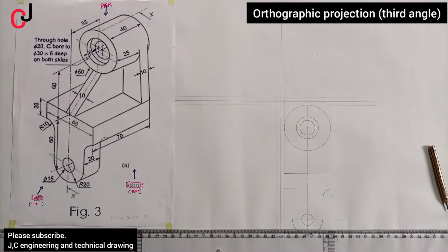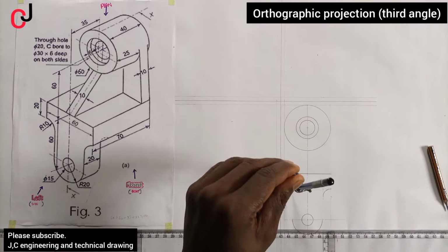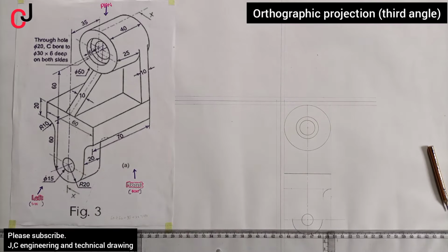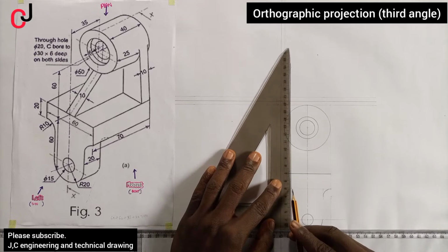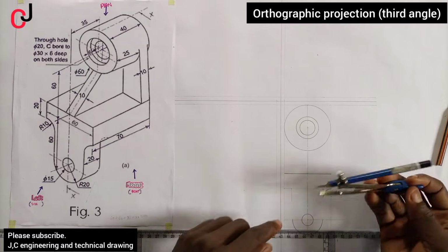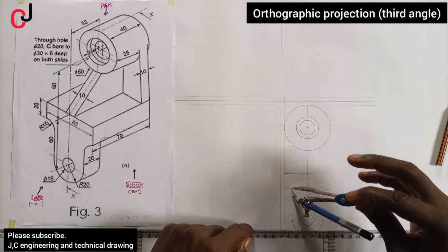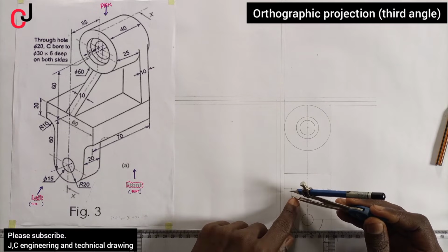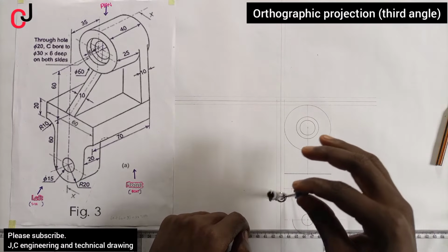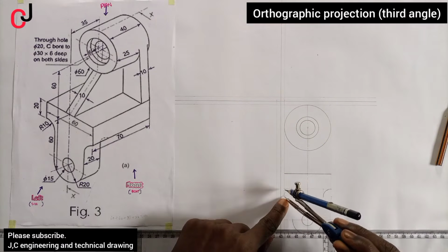Then you create your arc. So you do the same to your left-hand side, and then scribe an arc, indicate the point a little, and project that point downward to the construction line. Now using the same radius of 10 millimeter, create a point on the projected line, and then you bisect those points.